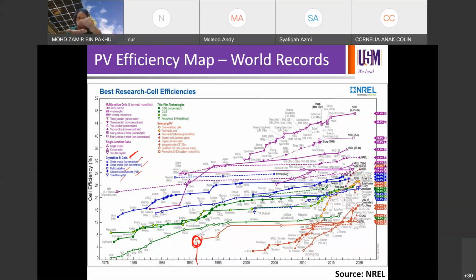You can place micro lenses and concentrate the light at all the locations. You can even use nano lens to do the very same thing. That particular case is called concentrator technology, where you concentrate the incident light. If you're talking about solar cells or panels which don't use any lenses, then we are referring to the non-concentrator technology, like the blue one here.